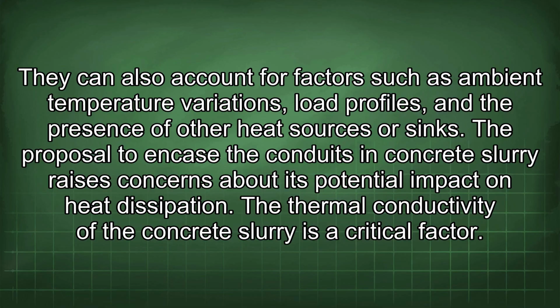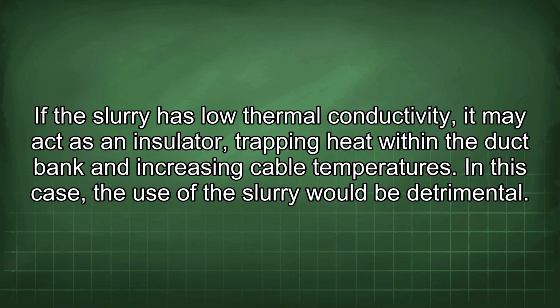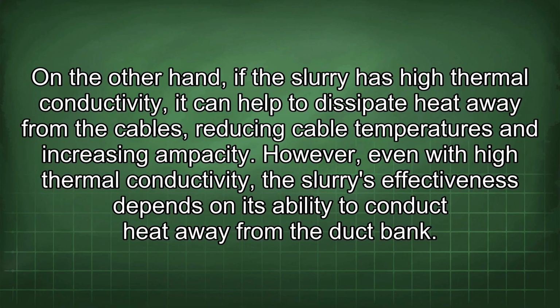The proposal to encase the conduits in concrete slurry raises concerns about its potential impact on heat dissipation. The thermal conductivity of the concrete slurry is a critical factor. If the slurry has low thermal conductivity, it may act as an insulator, trapping heat within the duct bank and increasing cable temperatures. In this case, the use of the slurry would be detrimental. On the other hand, if the slurry has high thermal conductivity, it can help to dissipate heat away from the cables, reducing cable temperatures and increasing ampacity.